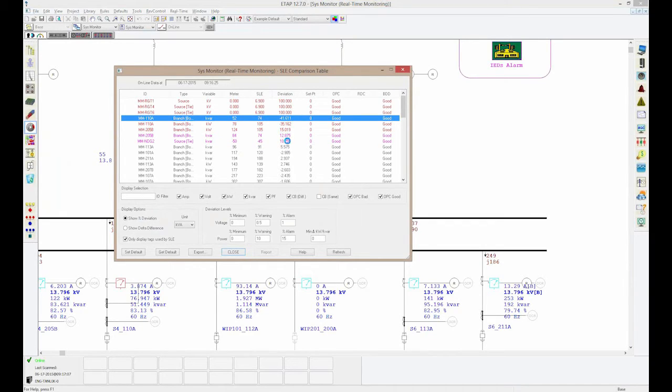And the smaller the magnitude of deviation in my table here implies I have a higher quality model. For example, the reason you may have deviations between the two is if you pull the cable, which is 500 feet in, and that's what's written in an AutoCAD file. And if you actually pull that cable in the real system, it may not be 500 feet. 500 feet was estimated at the time the system was designed. Reality may be 550 feet, it may be 450 feet, it may be different.